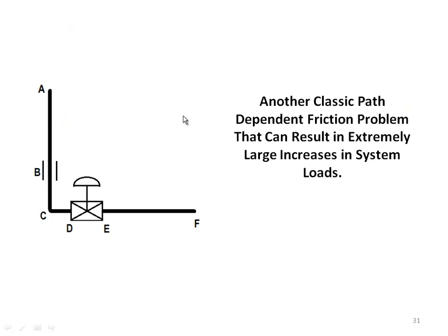For the case shown above, the leg from E to F heats first, closes and locks the guide at B. When the line from A to B subsequently begins to heat up, the guide at B is locked due to friction and high loads develop. It can otherwise occur in more complex systems when one part of the system heats before another part and closes gaps in the model which do not slide.